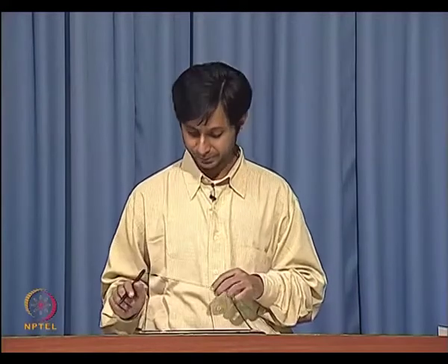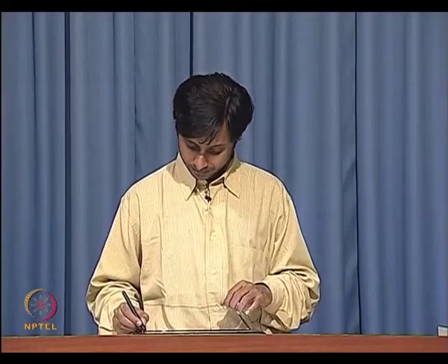Right. So, that is also one reason why you would be encouraged to generate both the transmit frequency and the receive frequency, the transmit and the receive LOs, in one shot using the same synthesizer, so that the frequencies are ratios of each other. Again, I will point you to a reference for this.